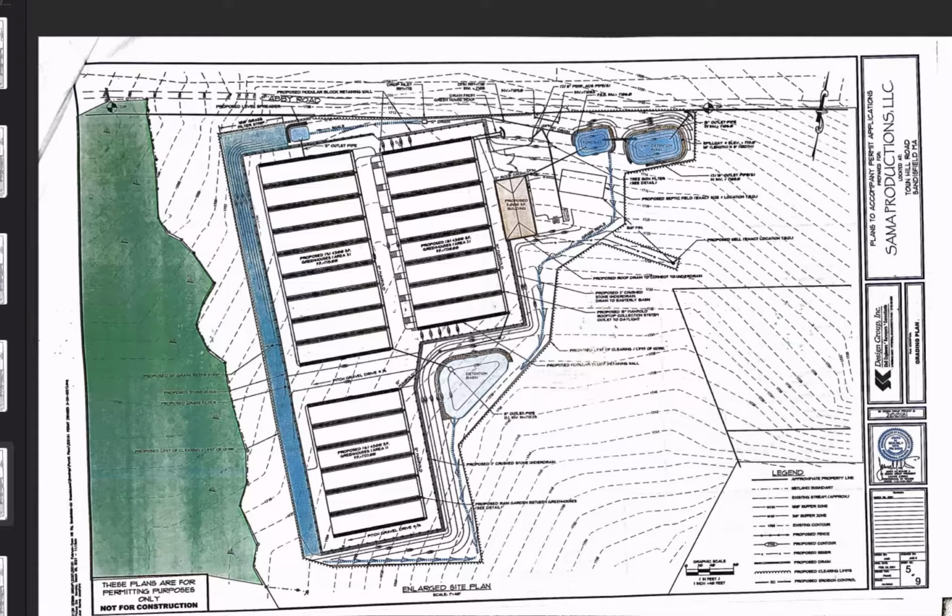So if this facility has 10 employees, they would expect that you would need 7 parking spaces. But also, rather than overbuild parking, which is considered under good land planning a terrible idea, I have 7 spaces, which is the absolute minimum at the 5,000 square foot building. So out front of this, there'd be 7 parking spaces.